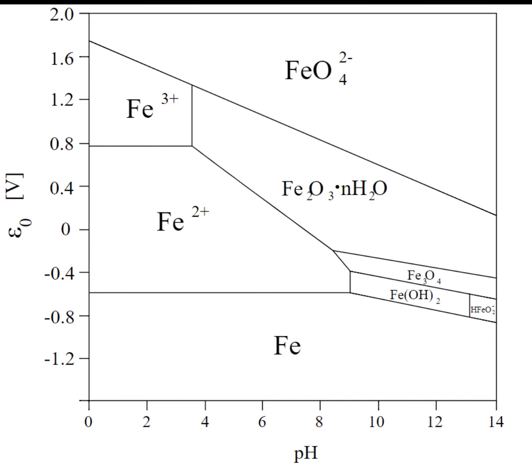So if we waited forever, that would be what we would get. That would be an iron 2 salt, but obviously we're going to form iron 2 oxide really close to our interface. If we go further out, we would see this magnetite, Fe3O4, and then we would see iron 2 oxide. So we would see exactly the same case going through as electrode potential through our surface to our iron.